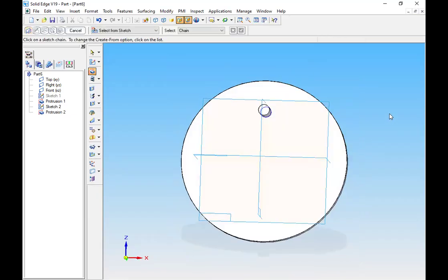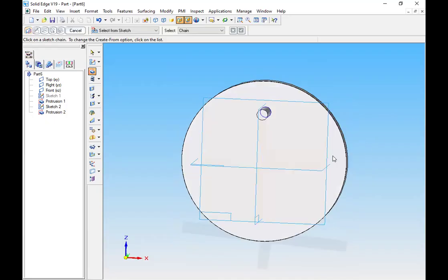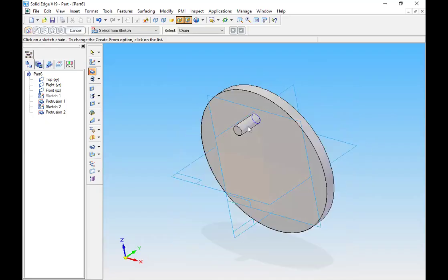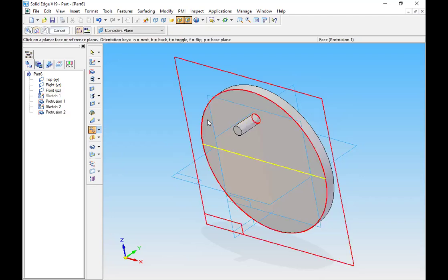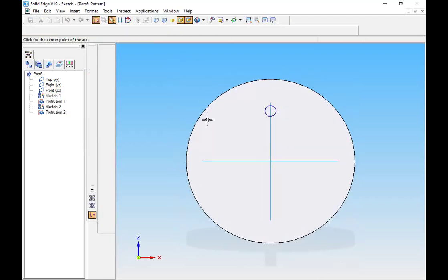so I have one pattern here, one circle pattern. I want the same feature, means this circular shaft what I have extruded here, in a 100 diameter circle of 12 numbers, 30 numbers, 35 numbers. So you have no need to create all those things. Using patterns, we can do that. Select pattern, select smart feature. Which one? This one. Accept. Where? On this plane.